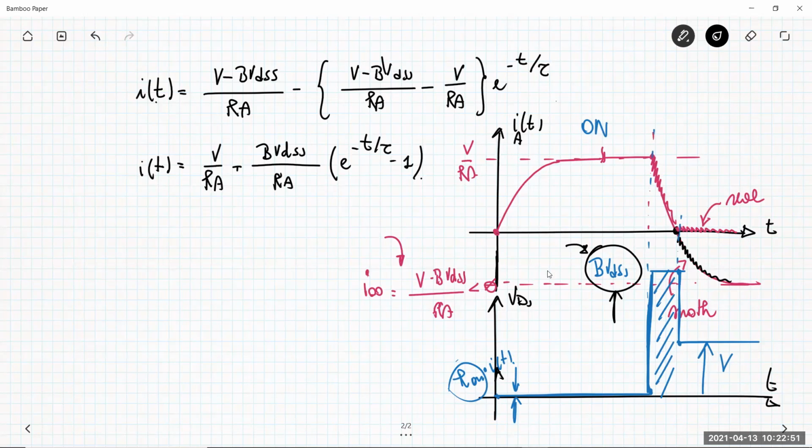So before reaching the maximum temperature permissible for a semiconductor, 150 degrees for example, it takes some amount of time. If you are able to operate the semiconductor device in the breakdown region with a very small amount of energy involved, the temperature has no time to reach the maximum possible level, and so this is not inducing any permanent failures.